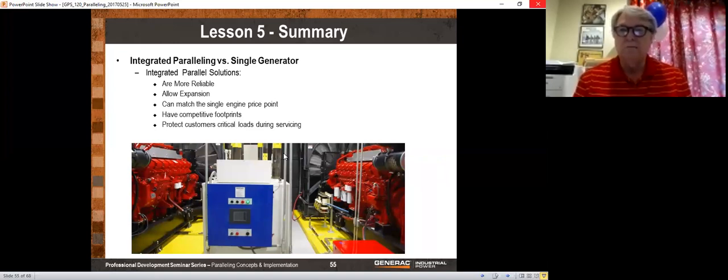And on that 6 month interval, you should also go out every month and just check the generator. This is generally done by the user. Feel the engine, make sure it's warm, make sure the battery's good and the battery charger's on, and look and see if the controller shows any faults, things like that. That should be done monthly. And then every 6 months, we recommend that someone who is a trained generator maintenance person does the maintenance. In some big facilities, they do their own maintenance. In most places, they will hire someone from a generator company to do that maintenance.